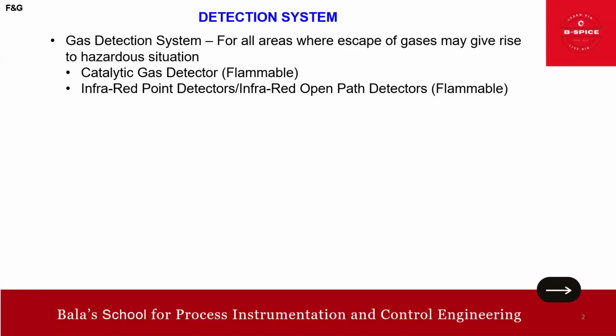The second feature of the open path is wide area monitoring. They are designed to detect gas over a large area, making them suitable for perimeter monitoring. It has a separate transmitter and receiver. The application is predominantly in petrochemical and petroleum for rapid gas leak detection.